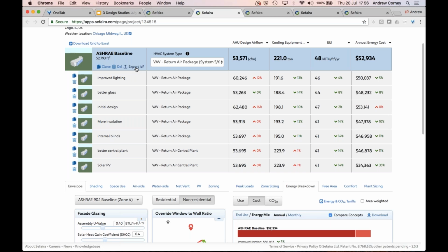Similarly, the daylight results are generated either using Radiance or DaySim. We create an analysis grid and then either use DaySim to do annual calculations on the analysis grid, or use Radiance directly to do point analysis within that analysis grid, and then reflect that in the rendering that we generate on the model afterwards.